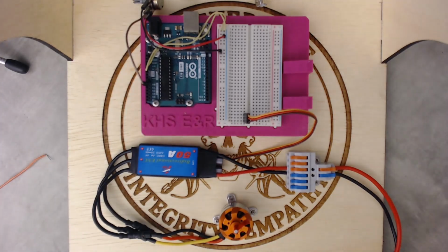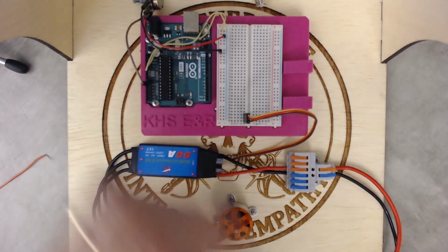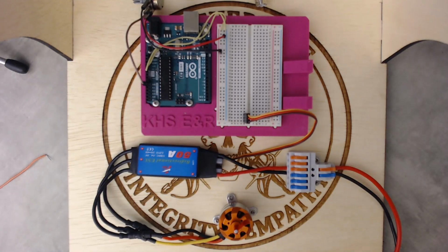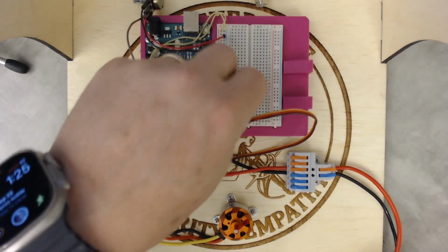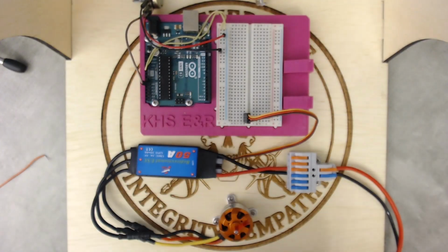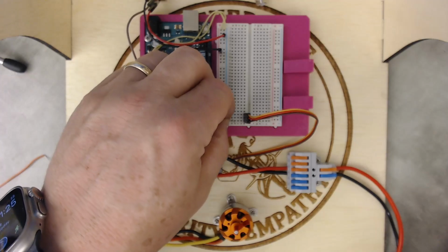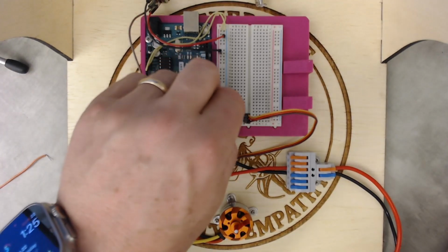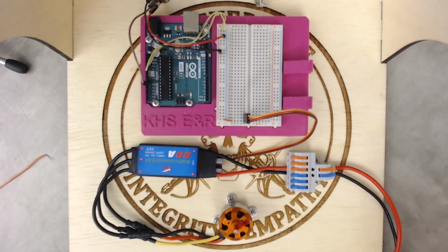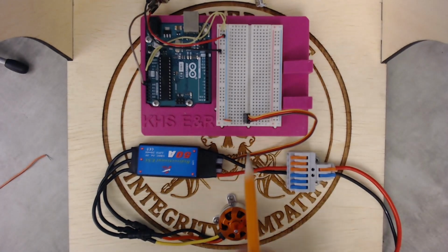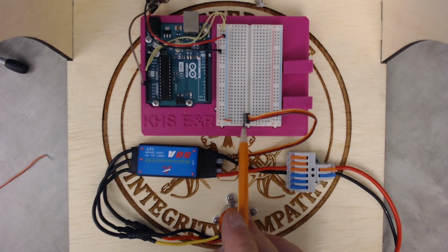So we're going to take a short jumper wire, and we're going to run it from the same row there as ground. I need a really short jumper wire. I'm going to connect that to the negative rail, because that's connected into a ground wire, over to that same row. So anything in this row is all connected together through one metal wire that's underneath all those pins. All these pins are connected. So now I've got ground connected to brown.